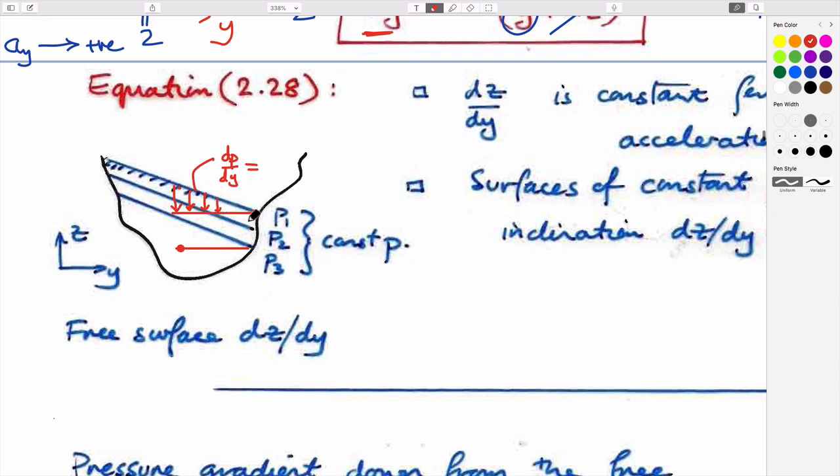If this happened to be enclosed, and this was open in a box to a fluid pressure, then you'd also see that along the top of this box, the pressure would change as a function of this. This is just rho A y, right? Just to finish that off. So it's a manifestation of the fact that if it's free to take a new orientation of the free surface, it moves like this. If it's covered by a container lid and can't do it, then it will develop a pressure which is 0 if it leaks out here, but it will build because of the acceleration from this boundary condition. And so that's useful to be aware of.